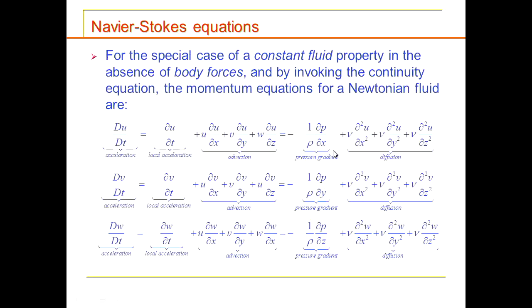But if you have a very large viscosity of the fluid and your fluid is very diffusive, then your diffusion term will be more dominant. So whenever your Reynolds number is high, because Reynolds number equals rho u something over mu, right? That means your advection term will be dominant. But whenever it's low, then your flow is more diffusive. For low Reynolds number, I give you an example like air. When I breathe, the air will always disperse. Why? Because the diffusion term dominates.